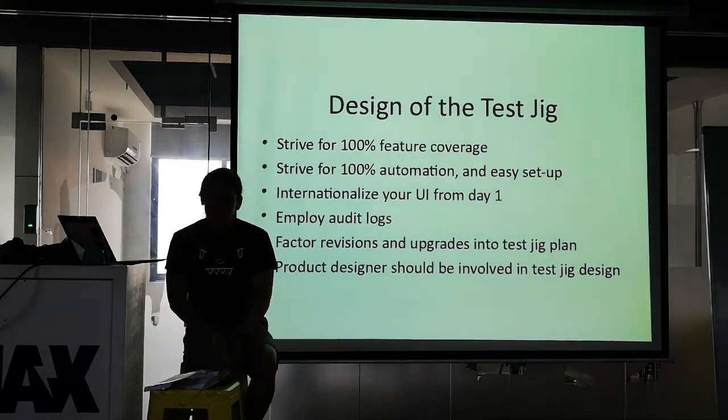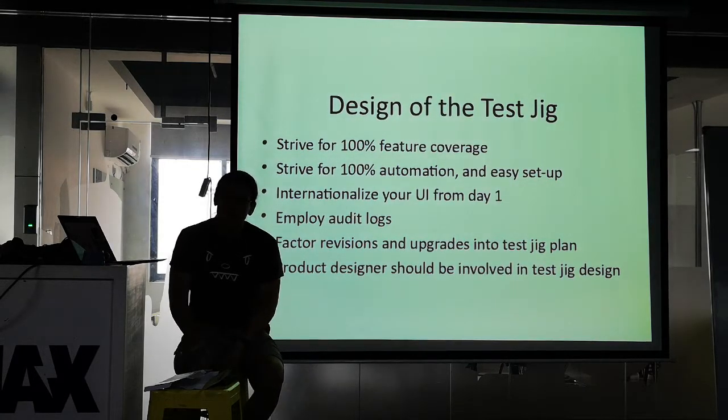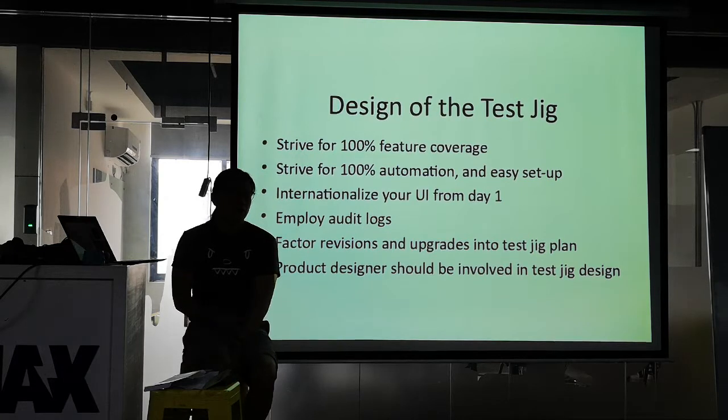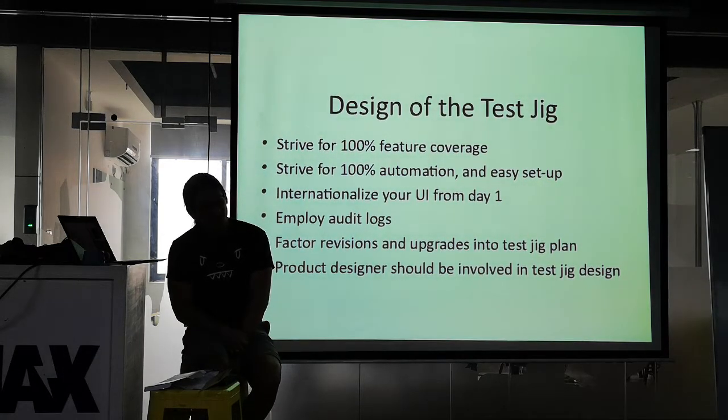For the test jig itself, if you don't know how to make a test jig and your product is very, very simple, like a badge with LEDs, you can just tell the factory, I need you to test if the LEDs work or not, and they can hammer it out for you. It'll be a couple hundred dollars or something like this. But if you have anything where you have to load firmware, pretty much you're going to have to do that firmware loading bit.